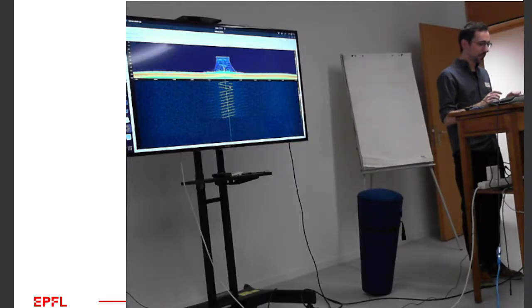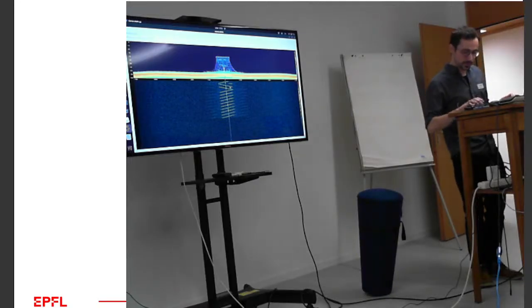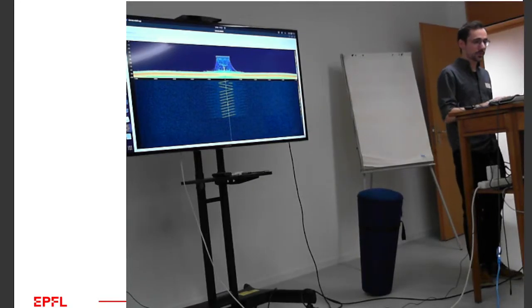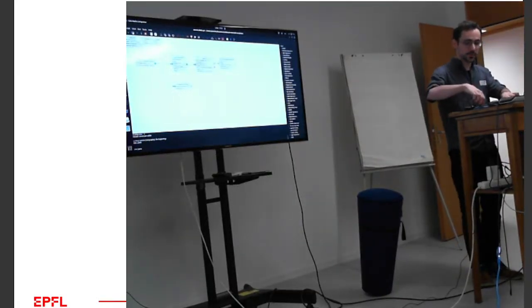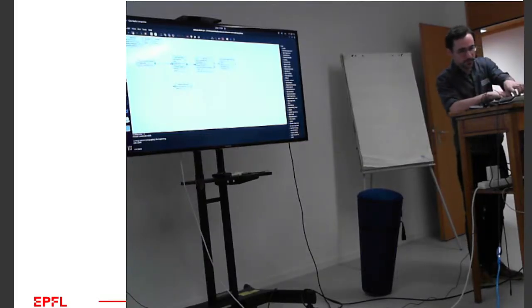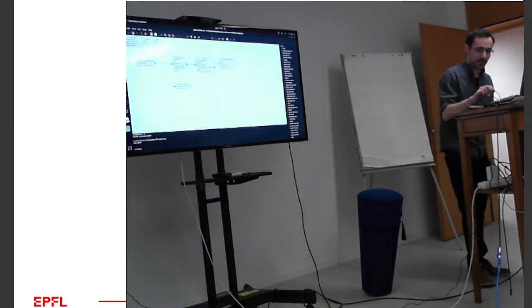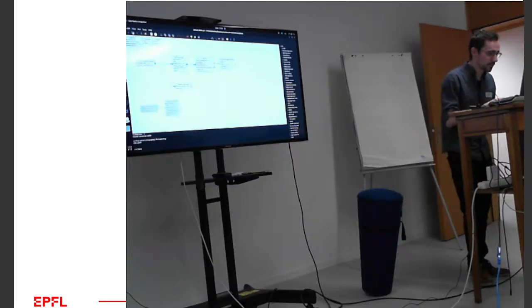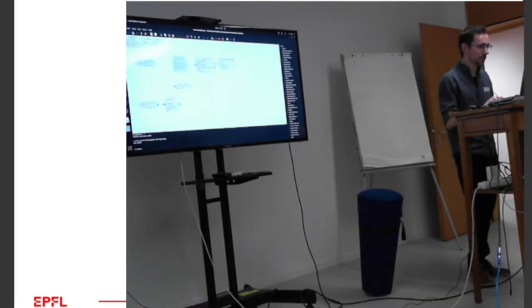But yes, so that's for the reception. I also have that working easily with just a cheaper radio. So here is the same flow graph that was tuned to the FM. So if I plug this one instead, and then wherever, I already prepared it. You just plug in a different block, and the low-pass filter is just to make it look nicer. You can connect it to the GUI to see it, and also to our receiver block.